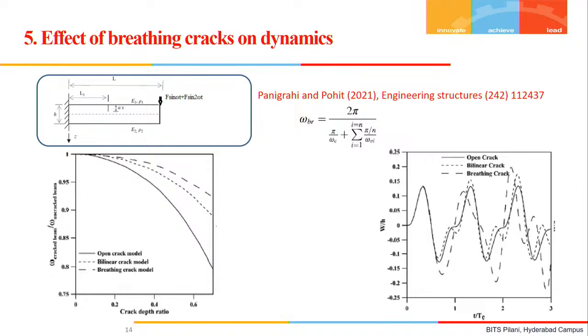So when we took this, we got the dominant frequency, and interestingly we performed the forced vibration analysis with that structure, and we found that the resonance was coming in the neighborhood of this dominant frequency. Although it was just an average, the harmonic mean, the resonance was coming in the neighborhood of this instead of in the neighborhood of any closed beam frequency or the completely open cracked beam frequency.